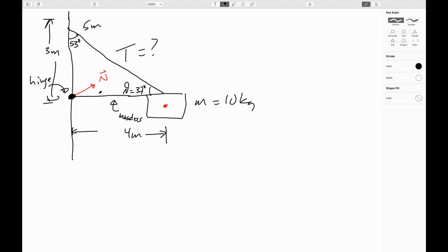Now you might think at first, wait a minute, why could it point in any arbitrary direction? And that's because if you look at the typical construction of a hinge, you have a pin and you have a follower sleeve around it. So the normal force is going to be exerted so the sleeve is kind of free to slide around the pin.